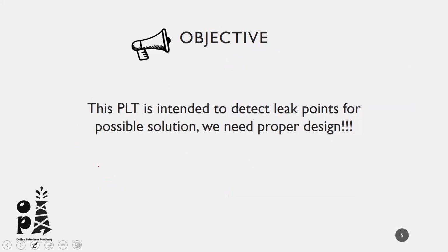So the plan now is to run with a BLT because our case is a new completion well with many gas lift valves that are prone to failure. So we must first identify the problematic valves, then change them directly. So the objective of our BLT is to identify the leaky points.